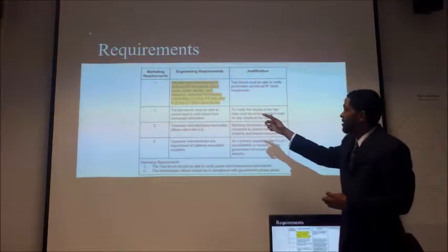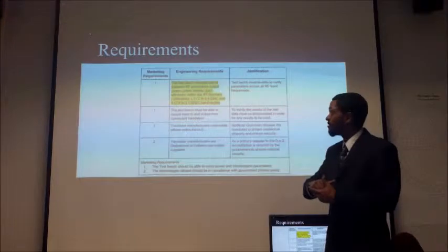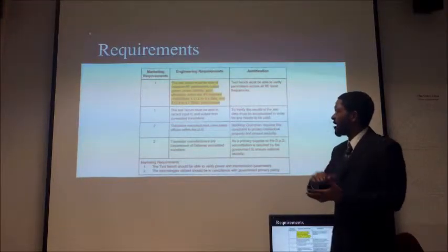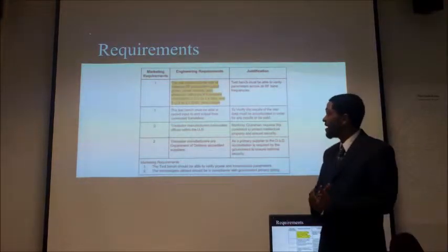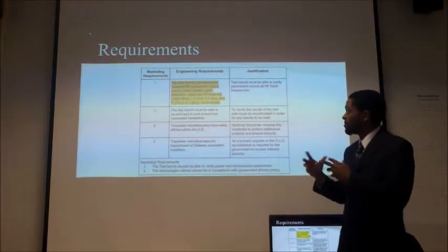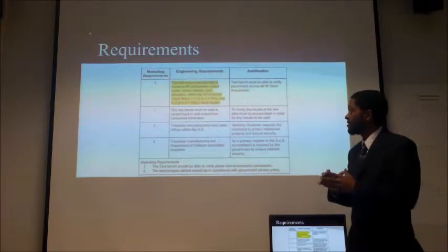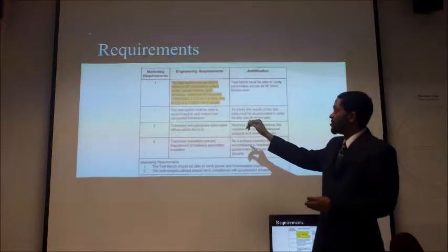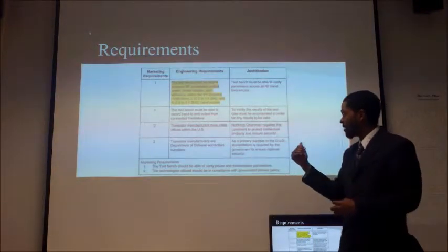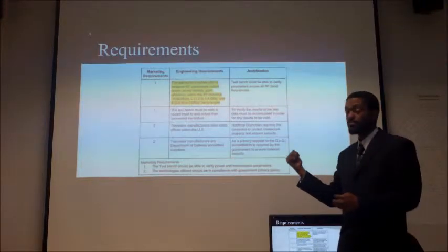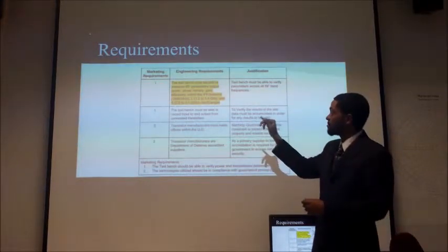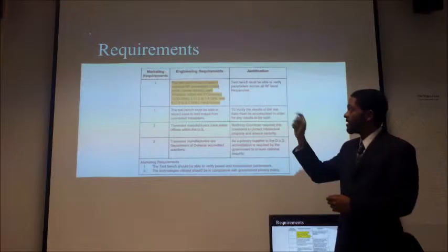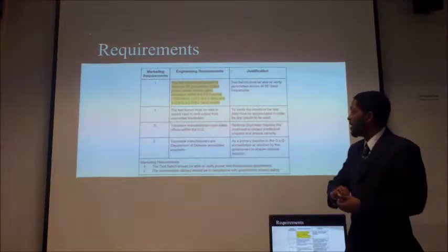The first being that the test bench must be able to measure RF parameters such as output power, power density, gain, and efficiency, and all these parameters must be measurable within the UHF band, L band, and S band. And then the other engineering requirement we derived from being able to verify power and transmission parameters is that the test bench must be able to record input to and output from connected transistors.